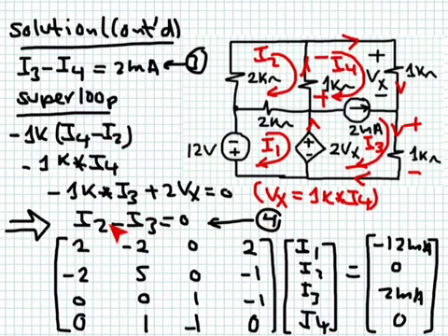So I write all four equations in a matrix form, and then I can try to solve it. Of course, I could have simplified it earlier. If I get rid of I3 and write it as I2 in all equations, I obtain a system of equations in I1, I2, and I4 only, which is going to be 3 by 3. So you can always make substitution and reduce the number of unknowns. Anyway, I kept it that way, and I used my calculator to solve it. And the solution is as shown in the next slide.